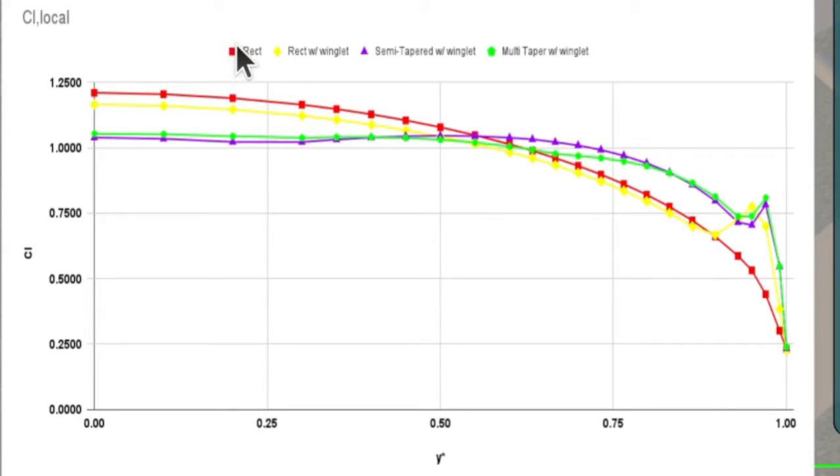Well, for the rectangular, it's going to hit it right here in the middle first. So that's really nice because that means the wing is going to stall here at the center first. And we like that because we like those ailerons to stall much later. That way, as we're approaching stall and start to get into it, the ailerons still have just a little bit of control to keep us from rolling too far. Now, if we put too much aileron input, that'll stall an aileron.